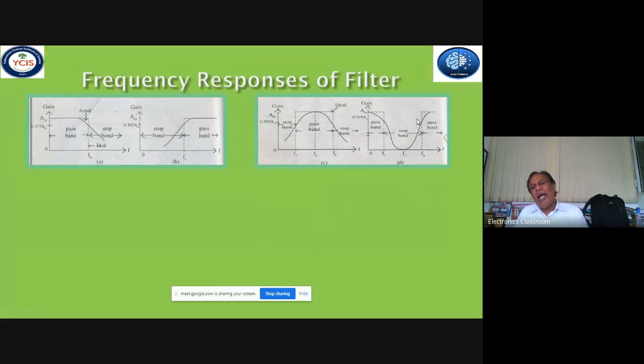In the band stop filter, the response is that of the parallel resonance circuit. You must have seen this circuit sometime. In the parallel resonance circuit, at frequency f equal to 0 there is maximum gain and output signal, then as frequency increases, the gain decreases. At some frequency the gain becomes 0, and as the frequency keeps increasing, the gain increases again. The frequency at which the gain is 0 is known as the anti-resonant frequency.